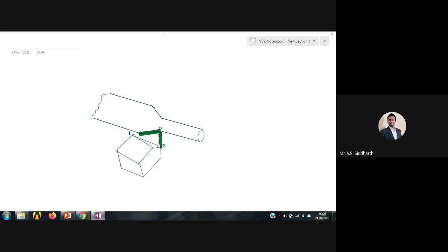We have given it some names. This 01 is known as the principal cutting edge, major cutting edge, main cutting edge. This 02 is known as the secondary cutting edge. So if, as per Tejasvi's answer, you are doing machining in this direction, then this will come in contact with the workpiece. But that is not the case. In that case, this 02 should also be called a principal cutting edge only.